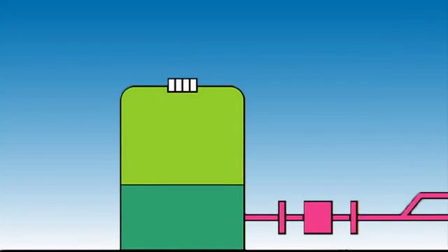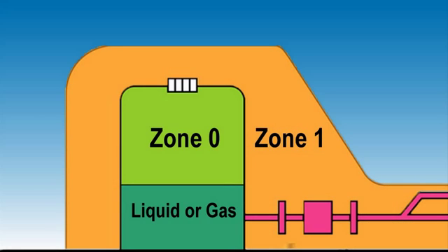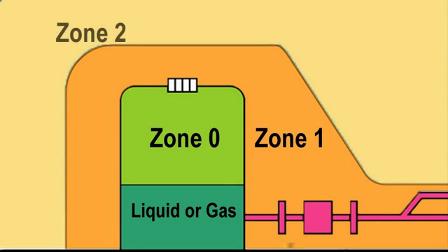In order to specify electrical devices and hazardous locations, we need to identify the general zones within each area. When working with liquids or gas, we locate the most hazardous or flammable location directly above the material. Due to the possibility of the valve leaking at the top of the containment structure, we must classify the area as Zone 1. As we move further away from the possible explosive atmospheric condition, the zone classification would be reduced to Zone 2.